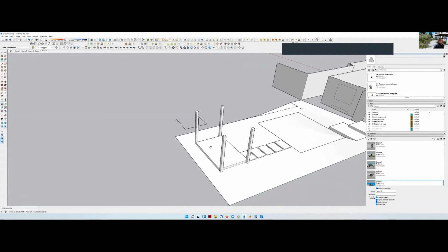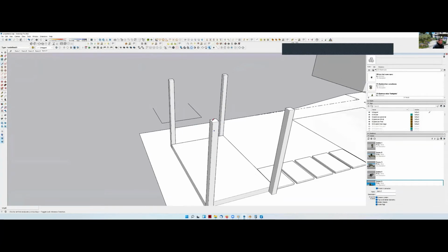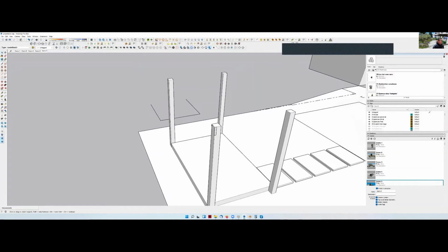SketchUp can actually geolocate your model to real life space, and based off of the actual position, you can actually do real life shadow studies, as long as your north arrow is properly lined up to the correct spot.